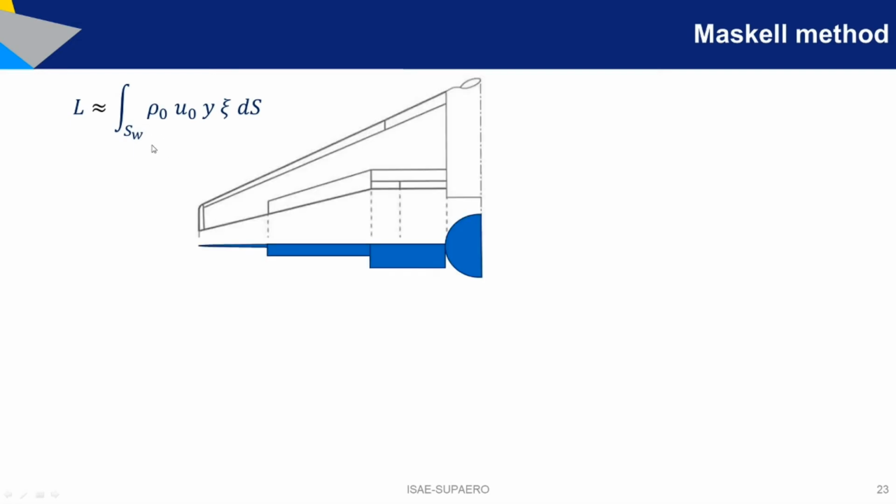So how does this help me to understand the physics, and how will it help me to do a design? Well, let's consider this wing here. This is the wing, the view from the front or from the end. Basically, what we have is the tip vortex here. We have another tip vortex at the end of the flap, another tip vortex at the end of the inner flap, and a counter-rotative vortex at the end of the inboard flap.